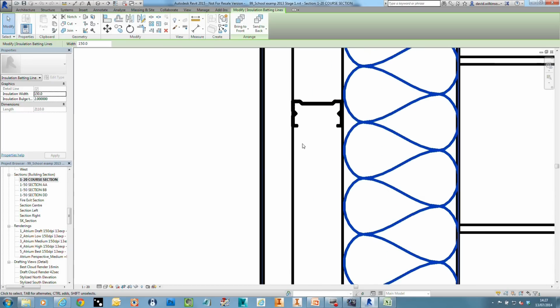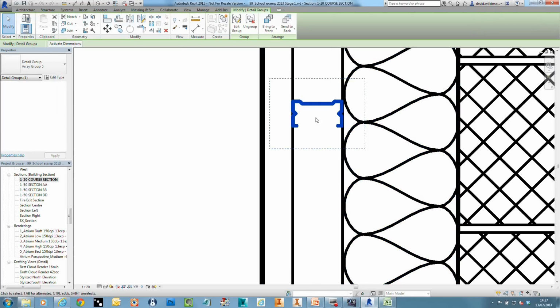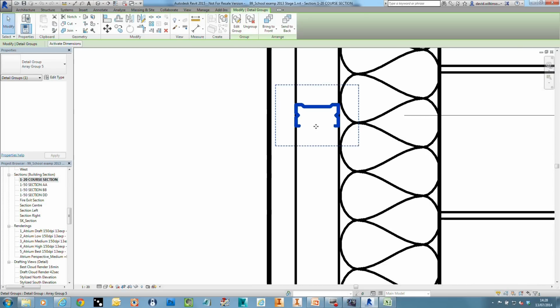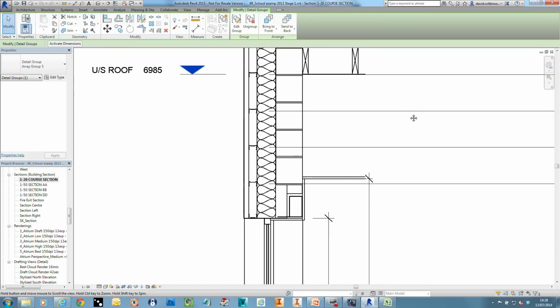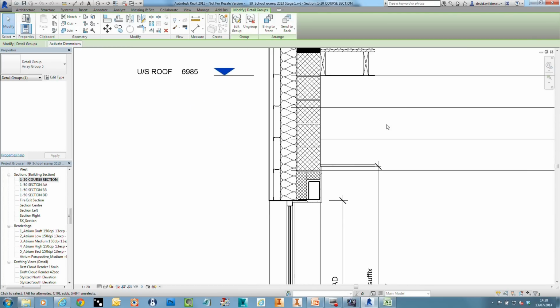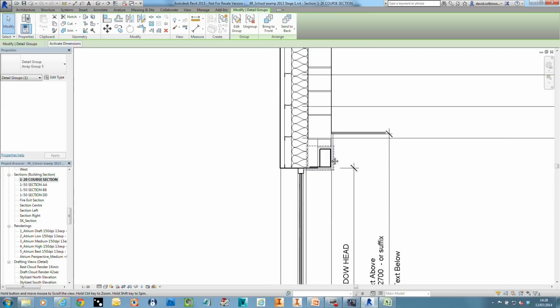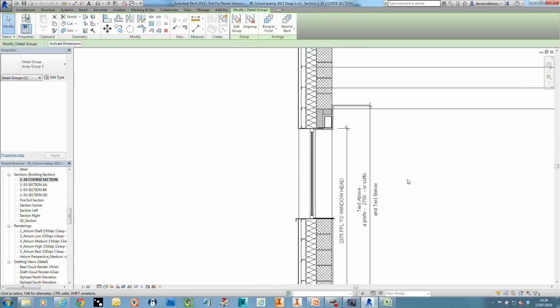But then if we want construction detail like here, then we pull that from AutoCAD if you like, or typically, you've probably got this sort of detail already drafted up in AutoCAD. We can just import that as a block in Revit and drop it down to show the right construction detail. Revit doesn't automatically do that for you. It's something you've got to go in and create in your views.